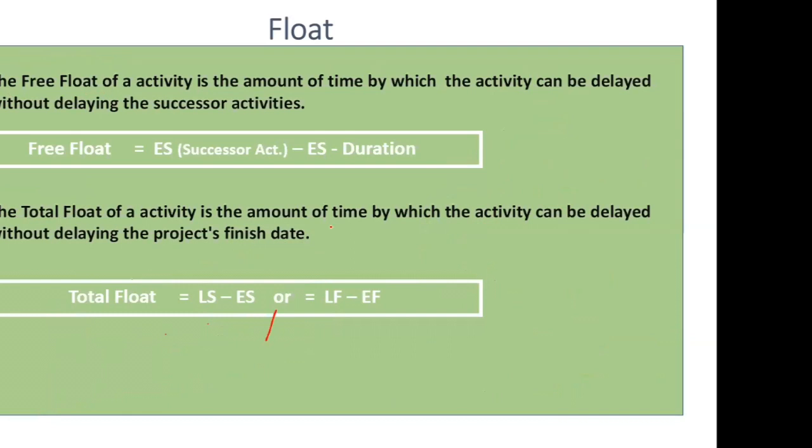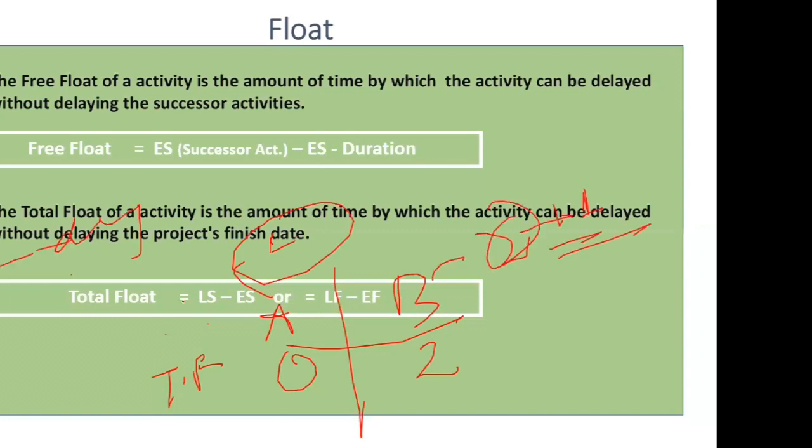So let's suppose there is a day when you have fewer resources available, or less labor at your site, and these two activities occur in parallel, A and B both. Then where will you prefer to send these laborers? Definitely to activity A, because you cannot delay this activity even a single day. If you delay this particular work 1 day, your project is really delayed. How are you able to make this decision? Because you know that the total float in this activity is low, and this activity is critical. You are able to make this decision when you have scheduled and you are tracking your project.